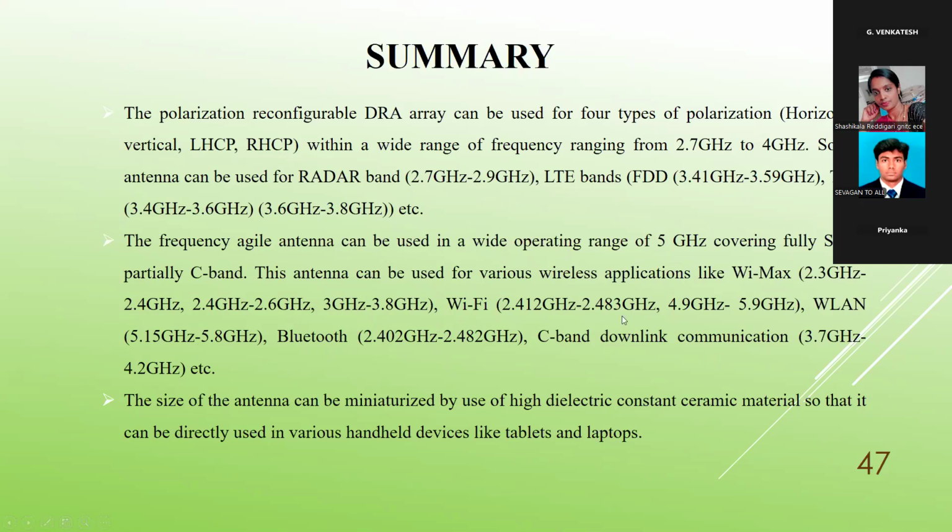So almost different bands of Wi-Fi, and C band downlink communication. And a very important thing is that the size of the antenna can be further miniaturized by using high dielectric constant ceramic materials. So it can be directly used for various handheld devices. So this is the non-fractal design.